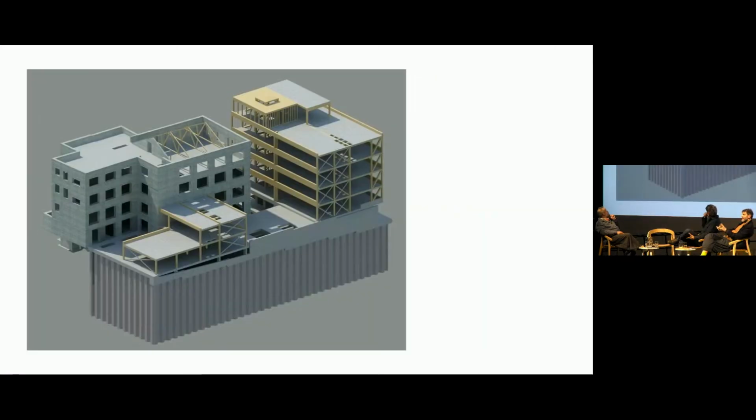So the UK, not that hot, not that cold. Many buildings are air conditioned. If the building is very lightweight, then it definitely needs to be air conditioned for some temperatures which are increasing. But if the building has thermal mass, it doesn't need to be. If people want to put thermal mass in the building, if you build it with a lot of concrete, you put a huge amount of energy into the building, much more than you'll ever spend on air conditioning, so it's completely pointless. So we were trying to modulate just enough thermal mass to remove the air conditioning with an otherwise low carbon frame.